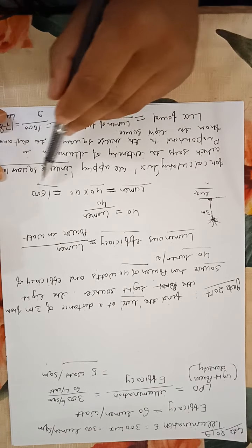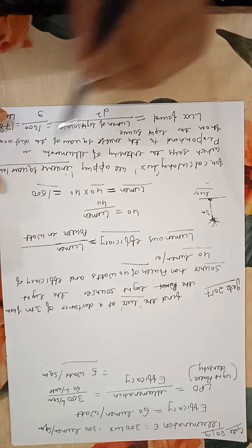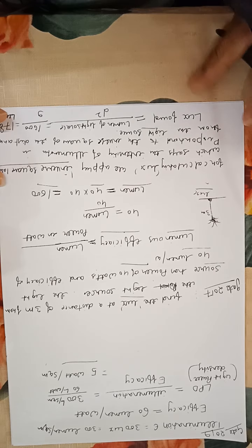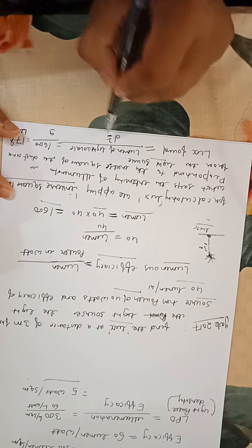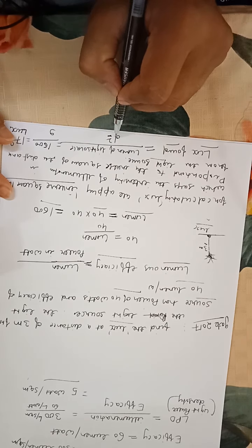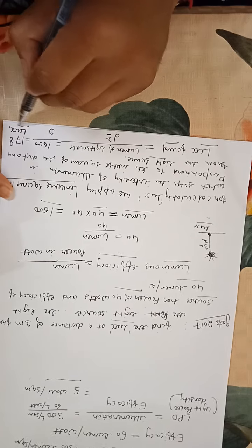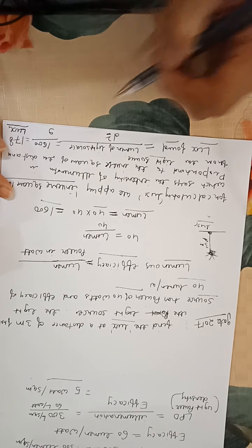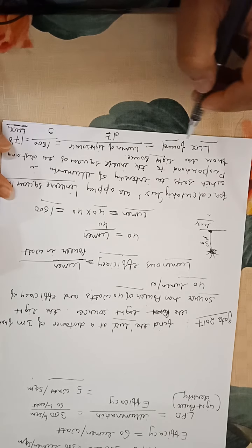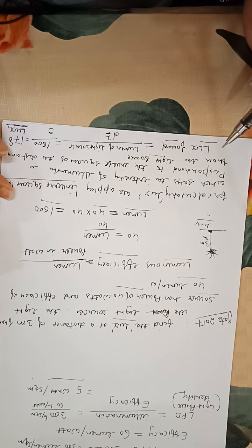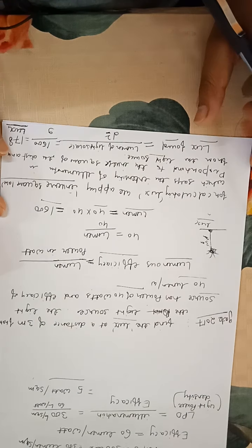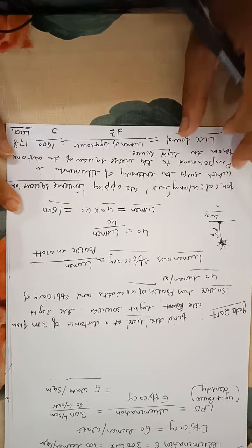So we found the lumen, and for calculating lux we apply the inverse square law, which says the intensity of illumination is proportional to the inverse square of the distance from the light source. So whatever distance from the light source is given, we have to square it, and lux is equal to the lumen of the light source divided by the square of the distance. So our lux is calculated, and lux is also per square meter of surface area. So that becomes lumen per square meter, and lumen per square meter is the lux. How much lux there is in a particular square meter, with the lumen of the light source being 1600. So this is the important one.